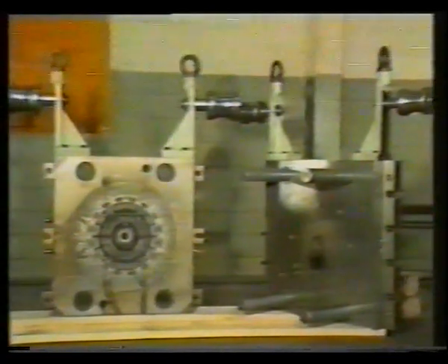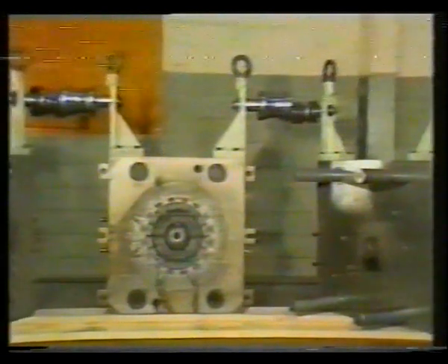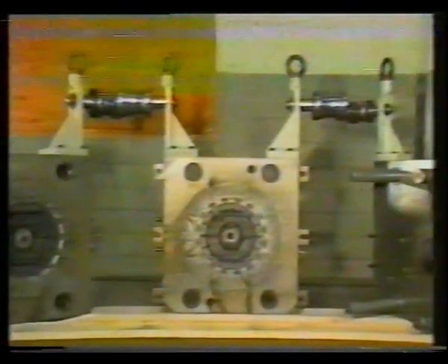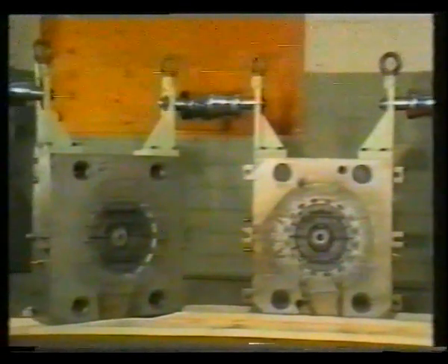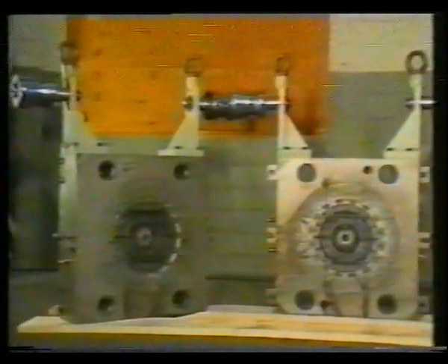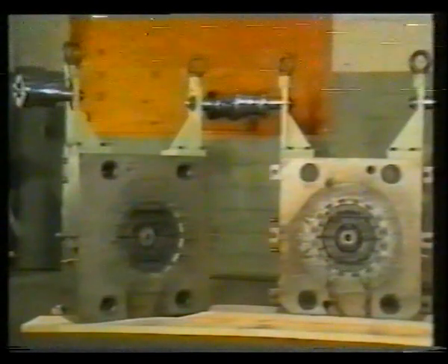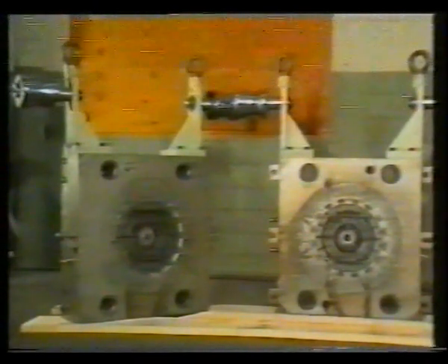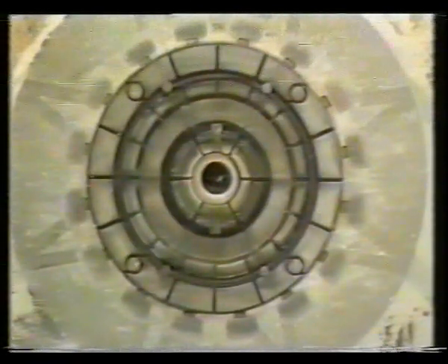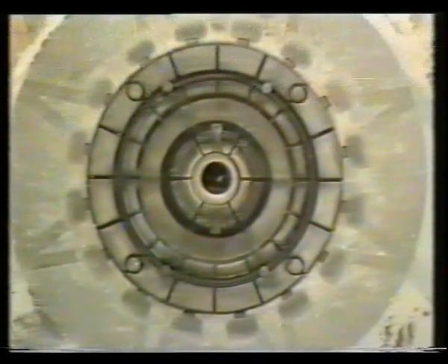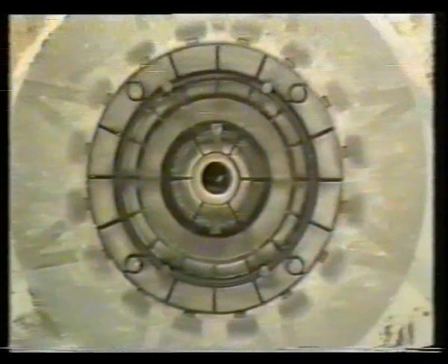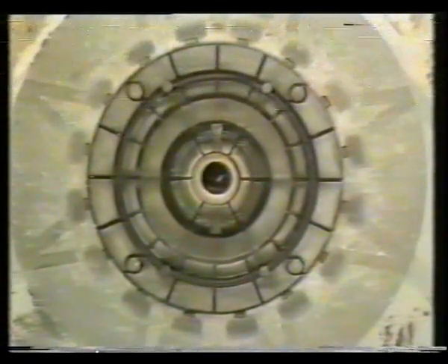The features of our quick die change system, in addition to machine-integrated die platens and the fact that the same die base is used as for the stators, allows productivity to be improved considerably. Thanks to the fact that the central runner has flow paths of identical length, ideal air displacement conditions, and thus sound castings are obtained. The low trimming requirements reduce subsequent metal cutting.